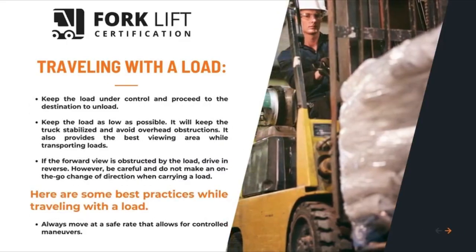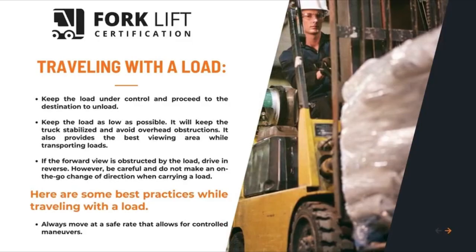Traveling with a load. Keep the load under control and proceed to the destination to unload. Keep the load as low as possible. It will keep the truck stabilized and avoid overhead obstructions. It also provides the best viewing area while transporting loads.